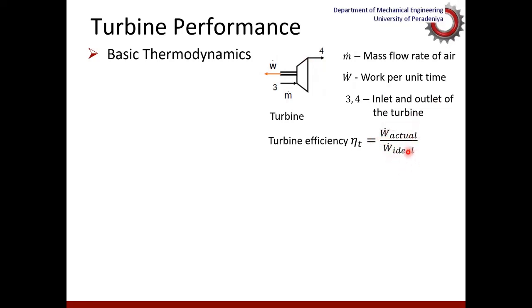So in this case, this is the opposite action to the compression, where in the compressor we have to give work to drive the compressor. Now the turbine gives out some work as a result of this turbine effect. So always the ideal situation has a better performance than the actual situation in the case of a turbine. It's the other way around in compressors.